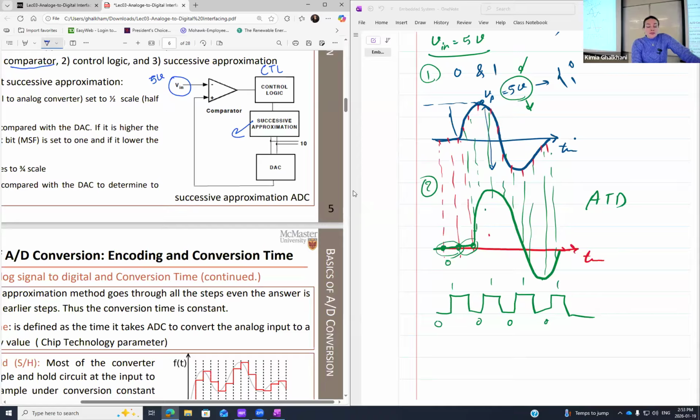For example, if it is, let's say, ATD0CTL, can you remember that was the address inside the lab? And that was inside the .h file. And before this .h, we had a long combination of letters and numbers, which is the name of the microcontroller. And then ATD0CTL was the control for the analog to digital.